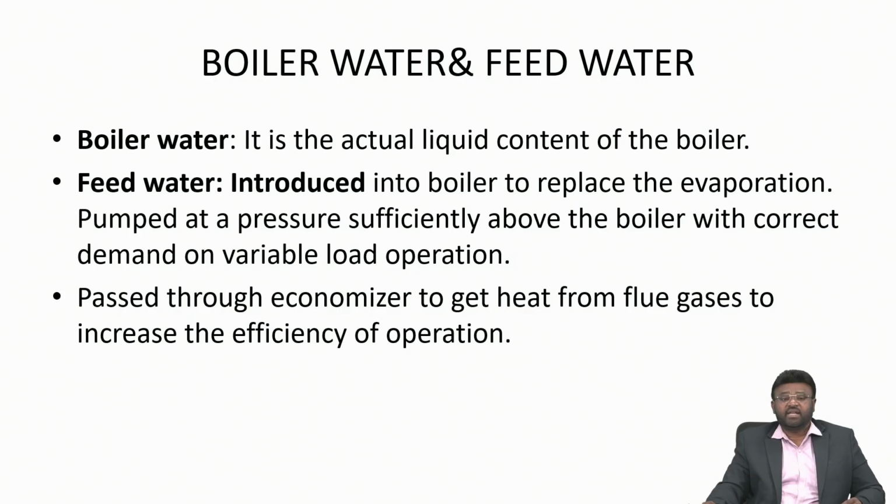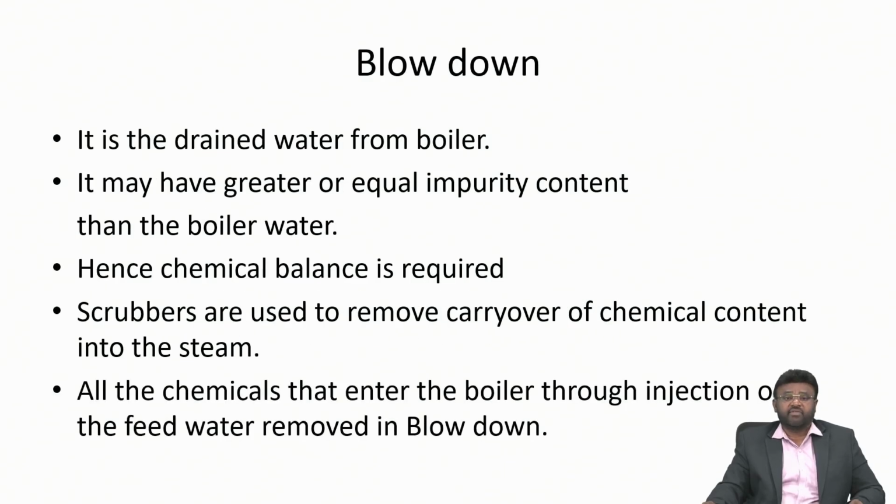The boiler water and feed water: the boiler water is the actual liquid content of the boiler, and feed water is introduced to replace the evaporation. So all these waters are very important. Another one is blowdown. Blowdown is nothing but draining the water from the boiler, because almost all the waters are collected at one place, which is called a blowdown tank.